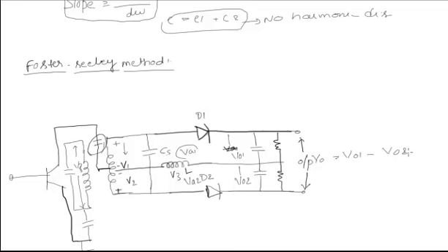The center tapping of the secondary has an equal and opposite voltage across each half. Therefore V1 and V2 are equal in magnitude but opposite in phase. So we have the equations VA1 is equal to V1 plus V3, and VA2 is equal to V2 plus V3. Depending upon the phasor relationship, we have three different phasor diagrams, and this will be decided depending upon the resonance.